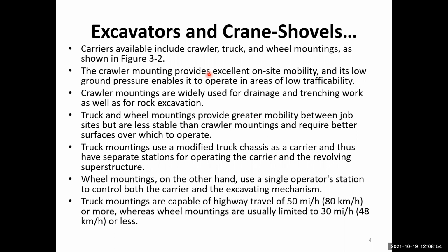Crawler mounted equipment is useful in those areas where the soil condition is soft, that means the conditions are for low trafficability. So in low bearing capacity soils, in those types of sites, crawler mounted machines may be used. The crawler mountings are widely used for drainage and trenching work, as well as for rock excavation.